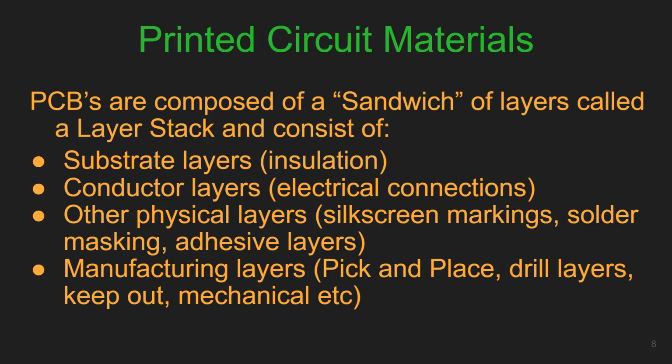and in the PCB, you can have multiple layers, starting from the single layer PCB, which has just the substrate, and on the top it has a copper foil layer. And the second one is double layer PCBs. It has substrate in the middle, and on the top and at the bottom it has copper layer.